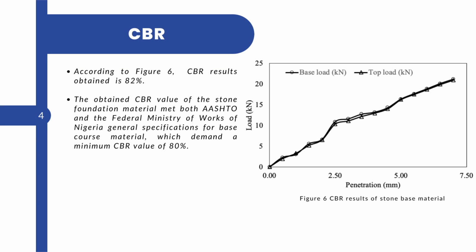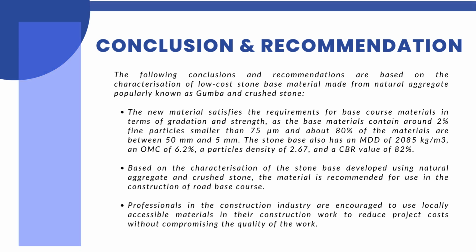In terms of CBR, according to Figure 6, we can see that the base load and top load almost meet at the same path. The CBR obtained is 82%, and based on AASHTO, the minimum CBR should be 80, so it meets the specification. Alhamdulillah.